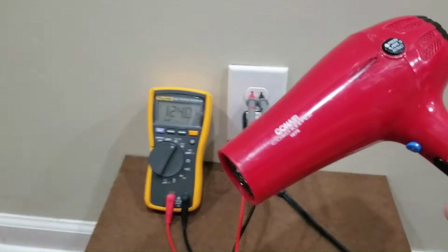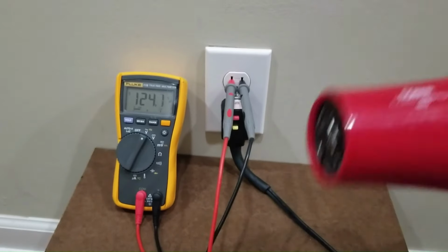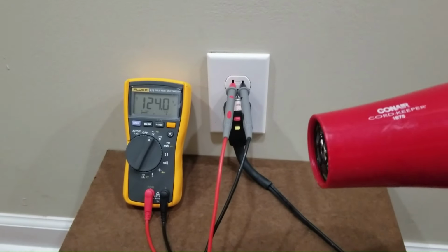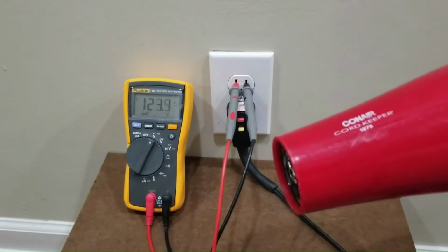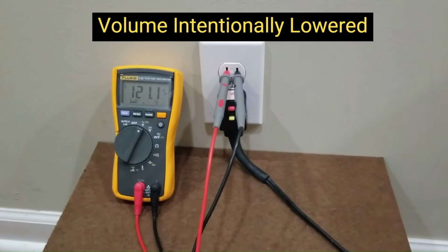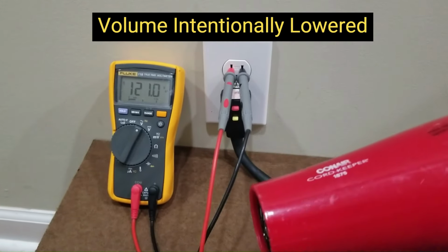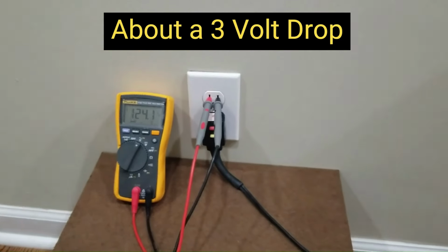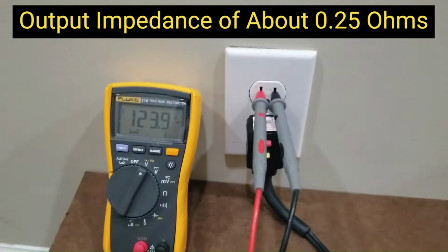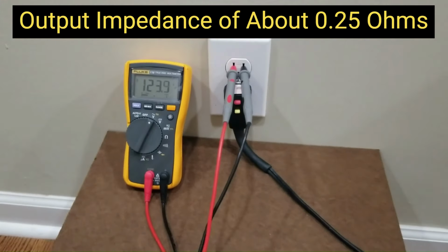So now I've got it plugged into this outlet here. And so based on our current draw reading of around 12 amps, we should get more than probably 1 to 5 volt drop when we turn it on. So it dropped a couple of volts there. That falls in line with what we expect our output impedance of this outlet to be.